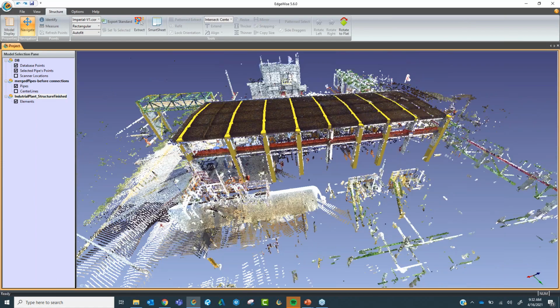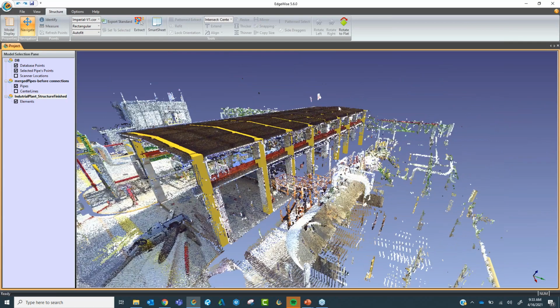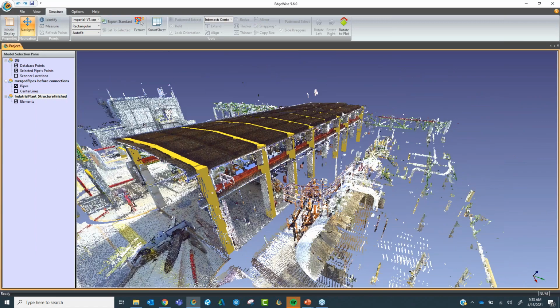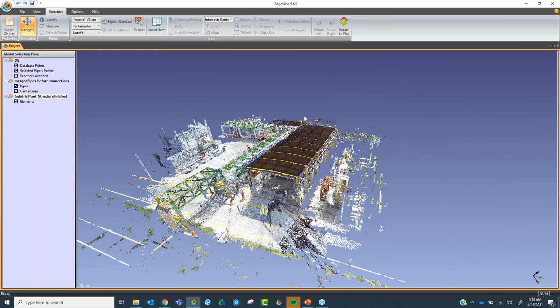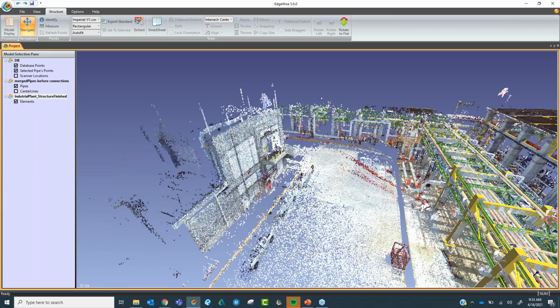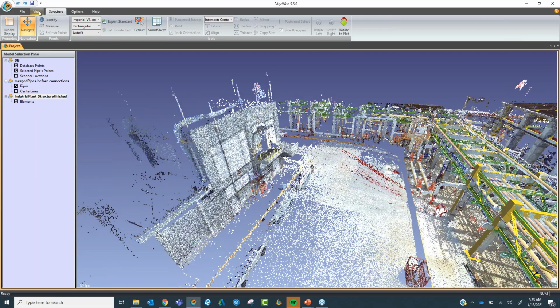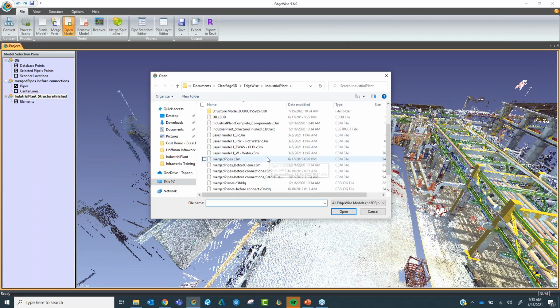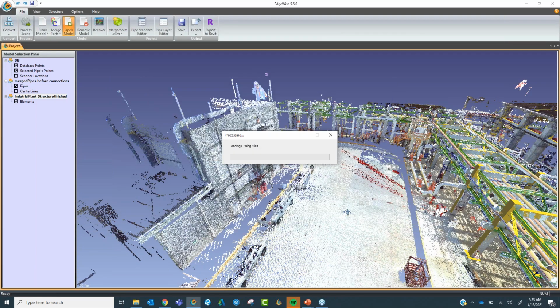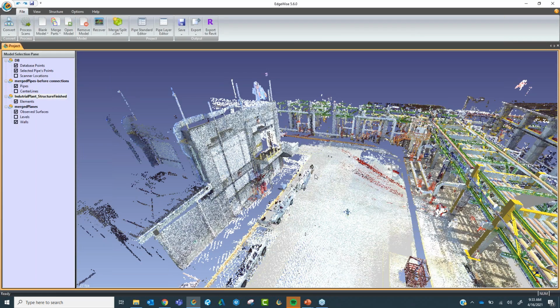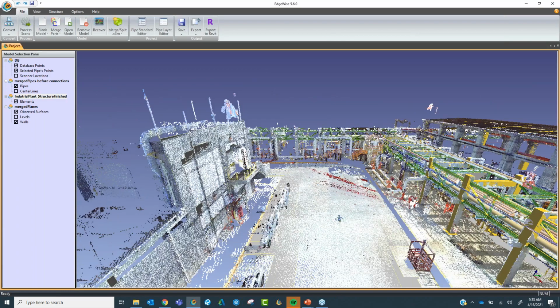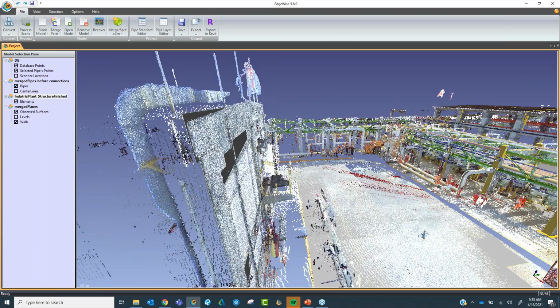All right. So that is bringing out our structural elements, okay? Now the building, you'll notice again, if we wanted walls, it does do that automatically. I will go ahead and open that one up as well. What's nice about the walls when we go to bring these into Revit is that Edgewise will actually typically go through and it'll try to mimic the wall exactly as it is.